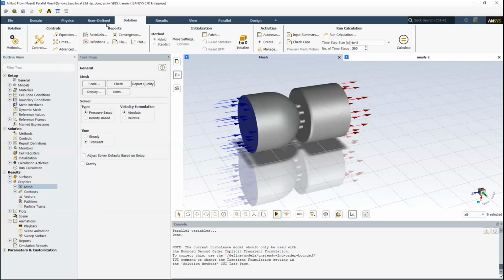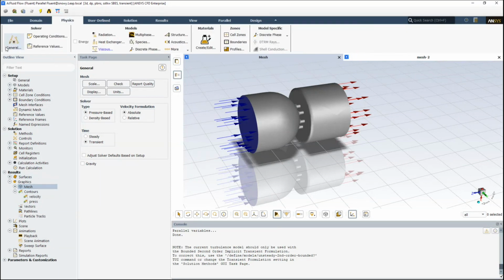Sometimes it's not possible because we don't have a stationary start point, but if we do, it's a much faster way for us to get a transient solution. What I mean by that is rather than running transient from the start, we'd start with a steady state simulation. We've got one steady state solution, and we've got a solution here already for that.